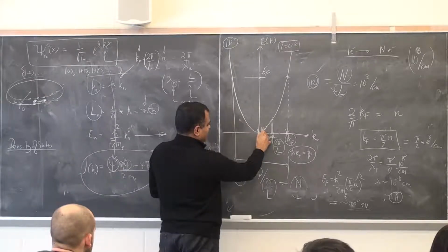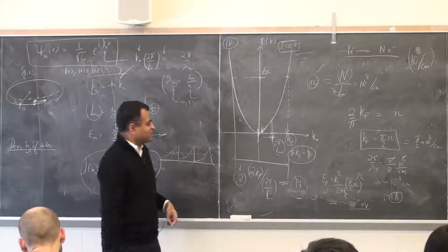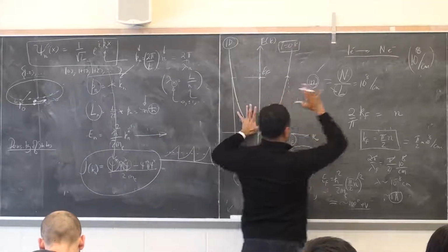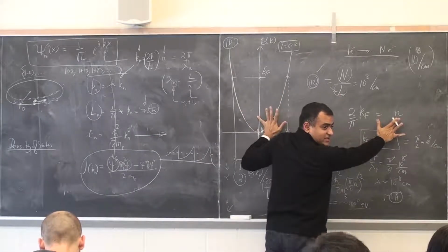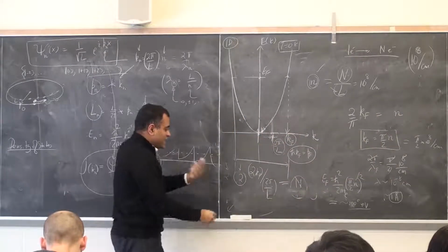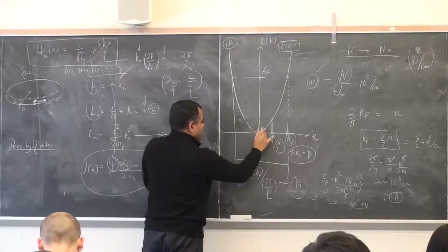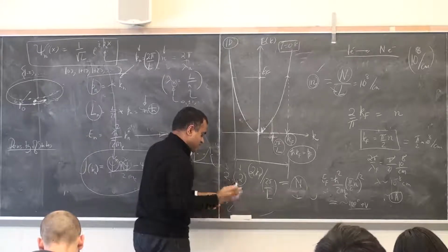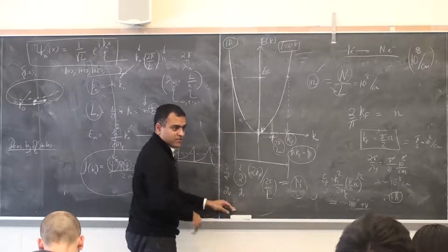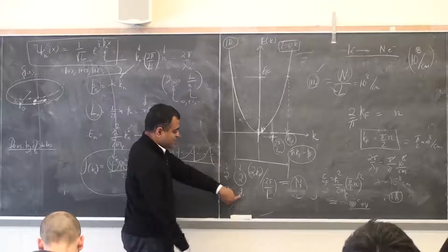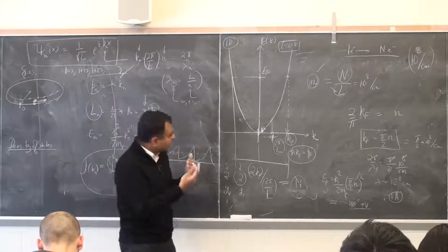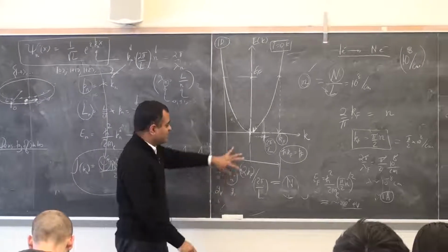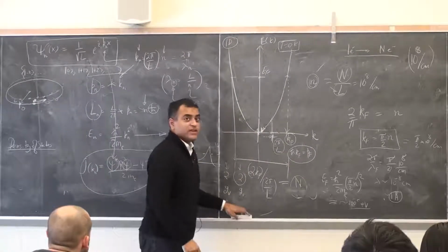So each state here, this is something we have not discussed, has 2 spins. Yeah, up and down spin. In fact, in a real carbon nanotube, there's another 2 here, which is because there is another copy of this in K space somewhere here. So that's called valleys, valley degeneracy. So spin will give you a copy of it, so you get 2. Typically it's written as valley degeneracy G sub V, spin degeneracy G sub S. You put them in, and whatever the situation, you go with that. Spin degeneracy is 2. If you go and look at a magnetic material, in some windows of energy it has only 1 spin. But here spin is 2 and valley is 2.